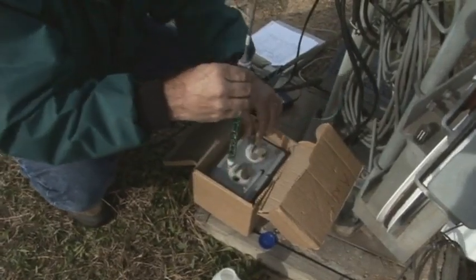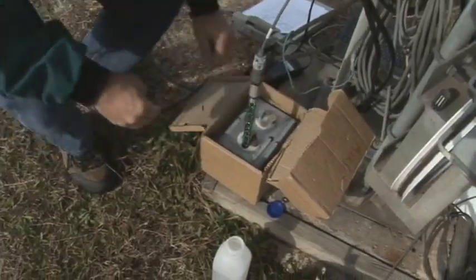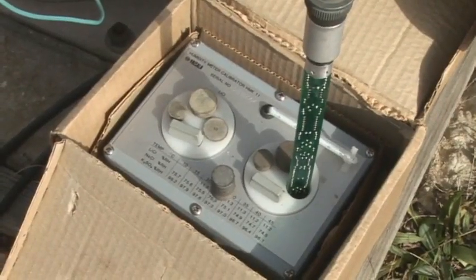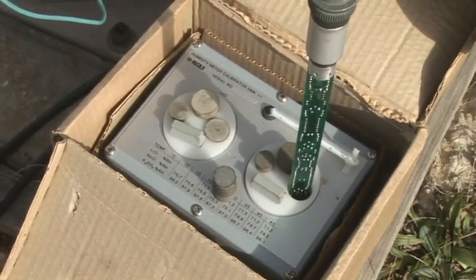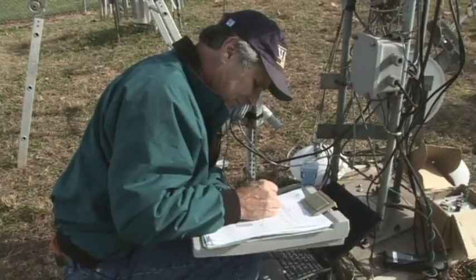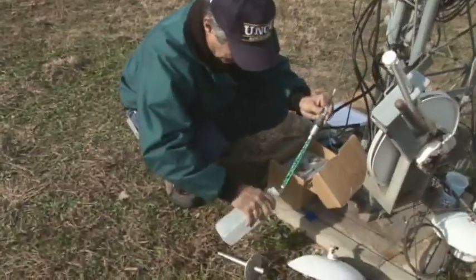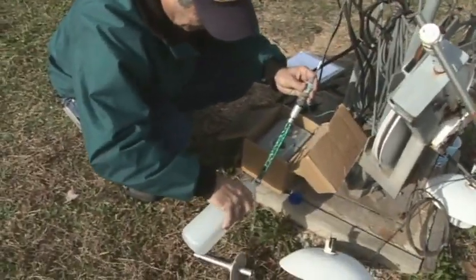Once the probe is removed and cleaned, insert the probe into the second calibration solution. Allow enough time for the sensor to stabilize. Usually several minutes are needed. Have the inside technician record the value from the DAS. Record this value on the calibration form. Once the system is stable, remove the probe and clean the solution from the probe.